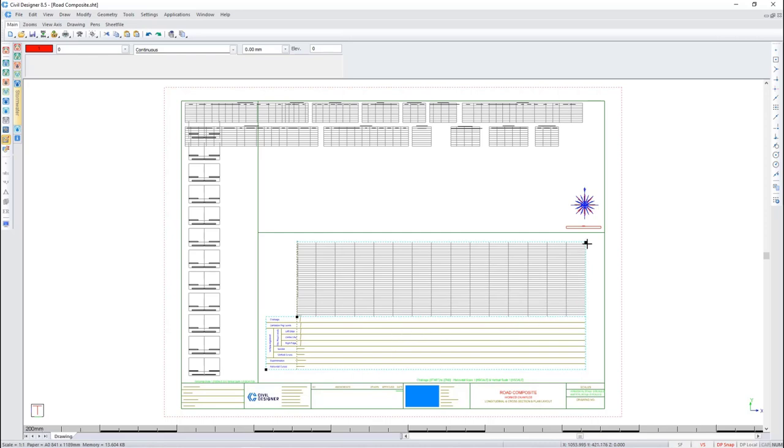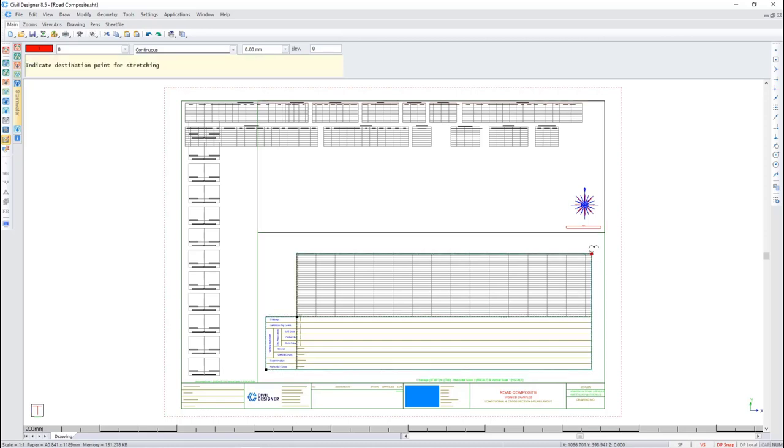The first handle that I'm going to look at is the top right hand side. You'll see that once I hover the mouse over it, I have the ability to then move it. I'm currently in freehand mode, and you do have the ability to use your geometry lines and snap using the geometry snap feature or any of the snap features. So you can really make this more accurate. As you can see, as I move this line, it will update the height of the graph area and the length of the data area.